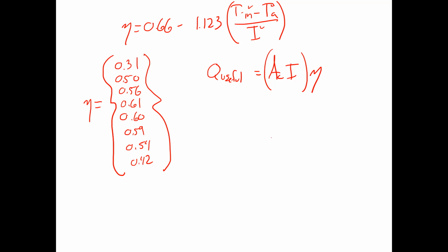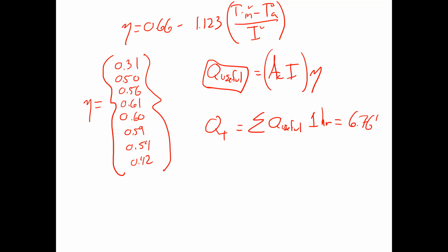Once you get this number hour to hour, you can just add it up, where you sum the useful energy, assuming that for each hour, that value is valid for the course of an hour. So if you do the right math and conversions, during the course of the day, you can get 6.76 kilowatt hours worth of total useful energy out of that solar collector.